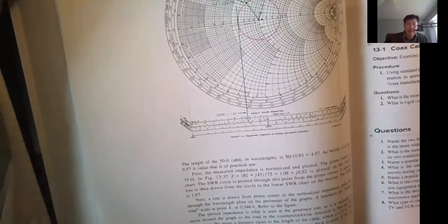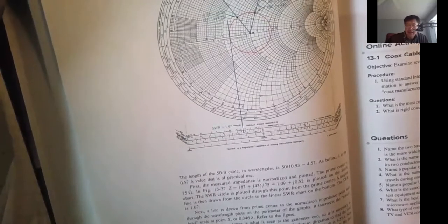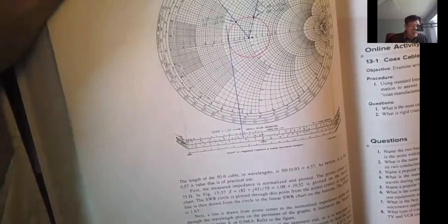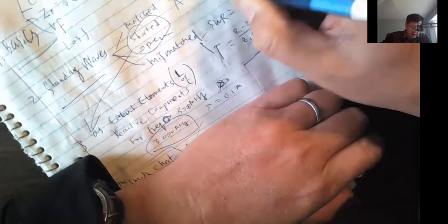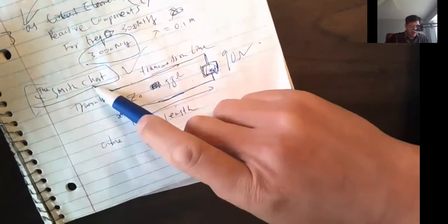The subject is pretty complicated because it's unconventional. It's something we're not familiar with. We as electrical engineers are used to analyzing DC power and AC power at 60 hertz. For 60 hertz, the lambda is thousands of miles. If you do the math, 3 times 10 to the 8 divided by 60, that is thousands of miles, if not hundreds of thousands of miles long. So the wavelength is really long. You would have to travel that distance to find the standing waves, to use it as a reactive component, or to use a Smith chart to evaluate the combined impedance.